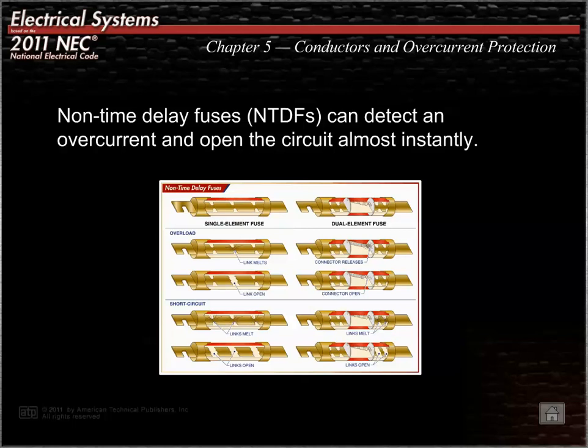Time delay fuses are designed to be used with utilization equipment, like motors, that are subject to temporary startup or surge currents. Time delay fuses allow overcurrents to exist for short periods of time to avoid nuisance tripping due to equipment startup characteristics.